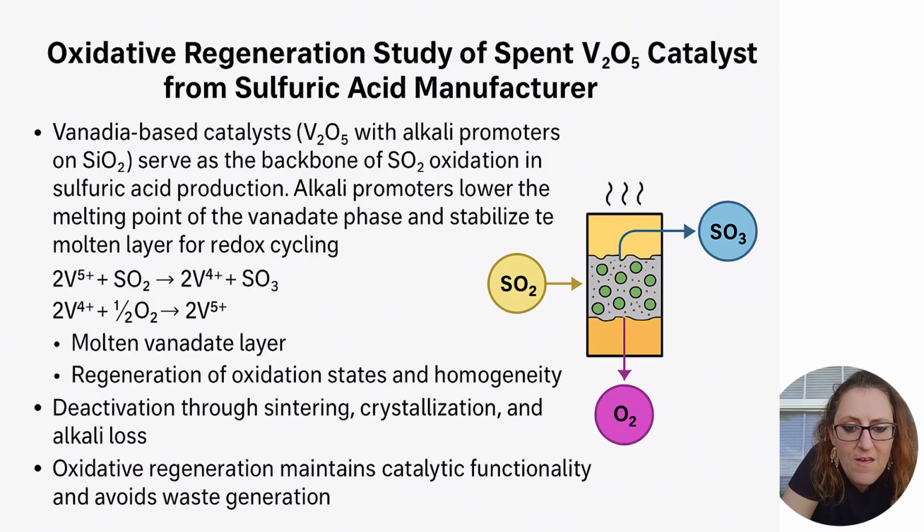This deactivation is a classic reaction engineering issue where thermodynamic stability competes with catalytic mobility. Alkali volatilization changes the molten vanadate composition, altering viscosity and diffusion rates within the catalyst layer. This results in non-uniform active sites and poor oxygen mobility.